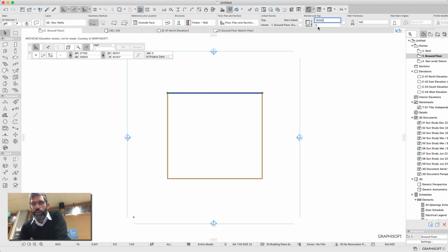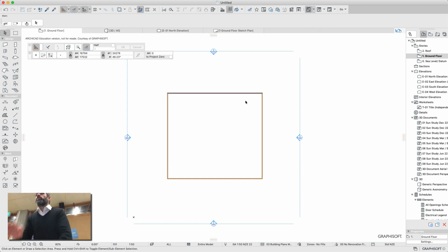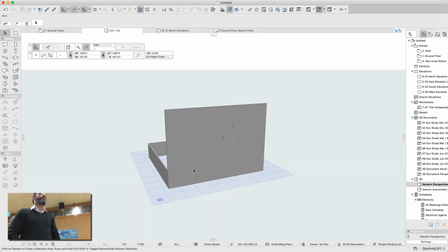That's the elevation off the ground. You'll notice that some things work a little bit different. Walls always start with 0 as the bottom of the wall and they go up to the height. So when you change the height, the top of it's moving. Whereas you'll find that concrete slabs work the other way around. 0 is the top surface of that slab and they go down. So if you go 300, they'll go down 300, okay? That all kind of makes sense if you're an architect. Okay, and if we go to the 3D view now, you'll see that one of my walls, because I only had one of them selected, has ended up huge and the others haven't. They've also got a whole bunch of other settings, because all those original settings are still in the old wall.